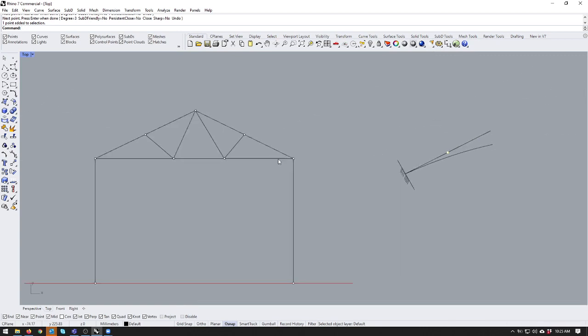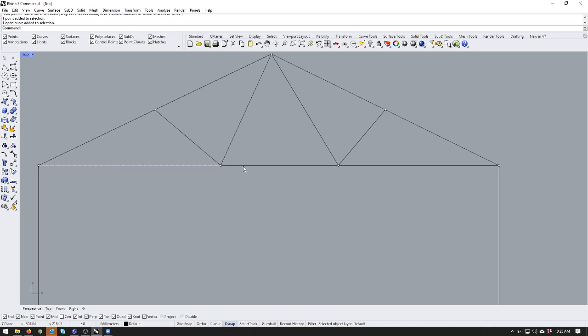So in this case, if we made the connection between these 3 objects a rigid connection, and we made these pin connections with this beam, then this would actually act as a single beam, because those rigid joints would transfer the energy the same way that having a single beam running through there would work. Yeah, that's what I was worried about. So if you make those pin joints, they'll act as 3 different things. But if you're making them rigid joints, it's going to act as 1, just with 2 joints in the side.